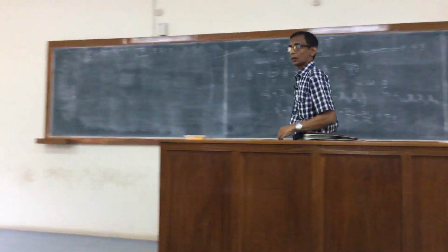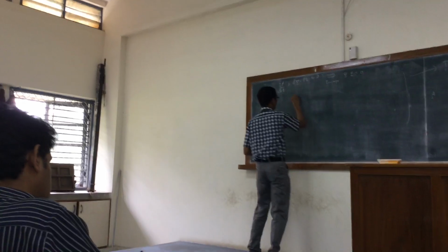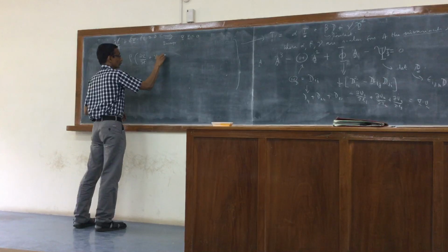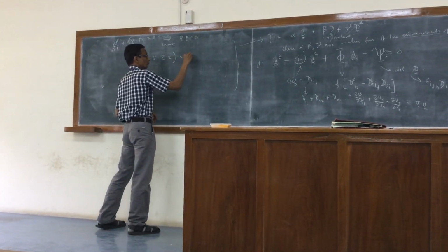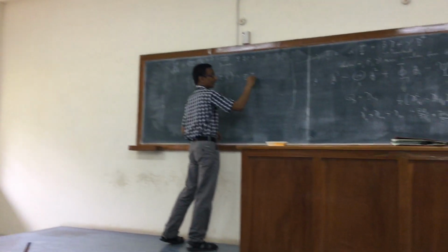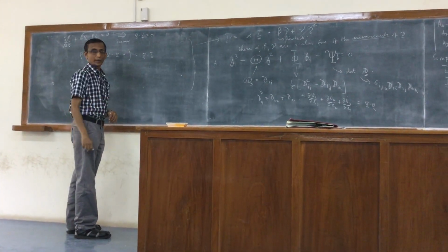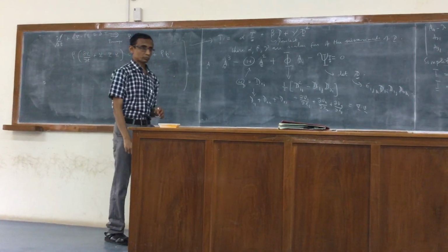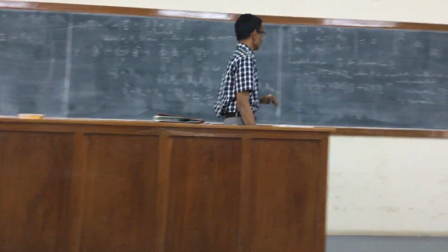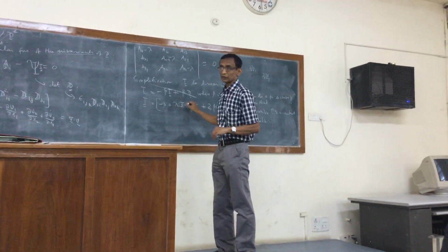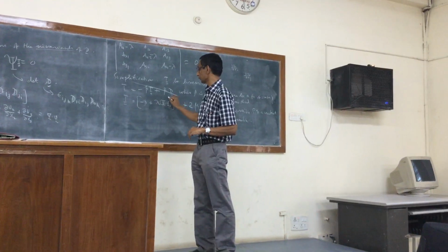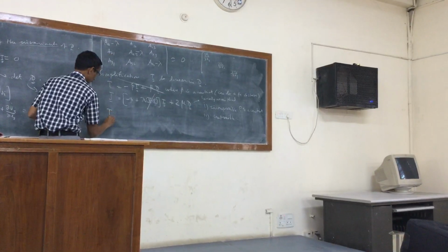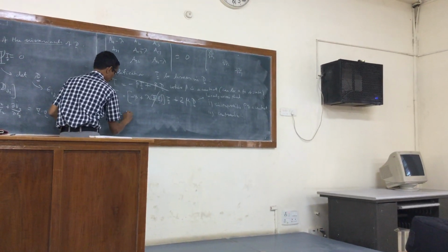And what about the momentum equation? That would be rho times the acceleration. Of course, for T, I have to now substitute whatever I have there, right? But the important thing to know is that now clearly, even if we directly look at this equation, obviously this will be 0 for an incompressible fluid. So for an incompressible fluid, I will get this very simple looking expression.